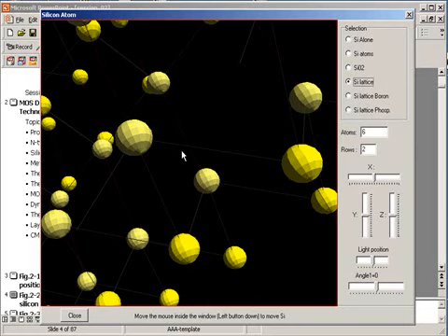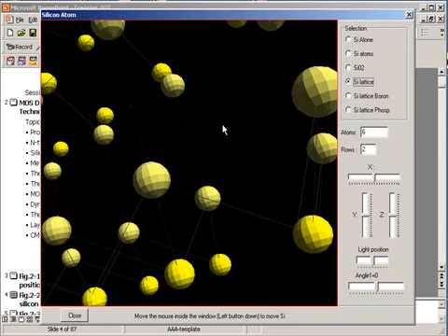And typically a valence electron of the phosphorus is released in the lattice when the phosphorus atom is inserted into the lattice. So the boron added to the lattice creates a hole, which is called p-type, while phosphorus creates a free electron, so-called n-type. Now, silicon dioxide is a natural and the most convenient insulator used to create IC.